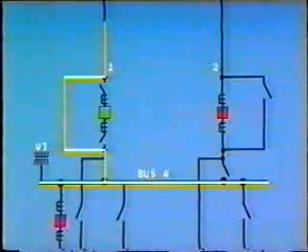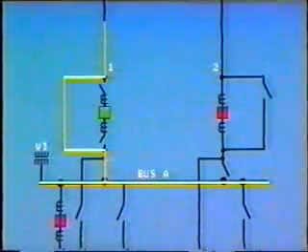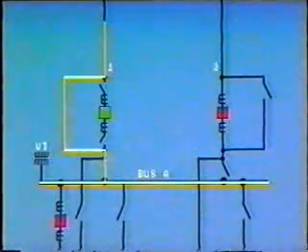The bypass disconnect on breaker 1 would now be closed, the breaker opened, and disconnects opened so as to isolate the breaker for maintenance. The transfer bus is connected to only one circuit. Note, before closing the transfer breaker, differential protection on both buses must be disabled, as there may be a current unbalance. As previously mentioned, bus tie protection must be adaptable to all lines.